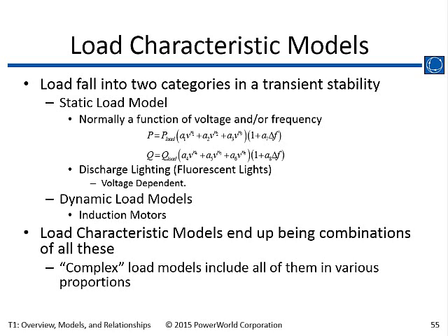So what do you do when you see the positive eigenvalue? You just click the sign or do something? Getting around to tuning parameters is a challenge. We do give you sensitivity analysis tools that you can figure that out with somewhat. It's not a simple thing to do. PowerWorld tries to make transient stability as simple as possible, but it's not a simple problem. It takes very intelligent engineers doing this stuff. It's not for the average layperson to do.